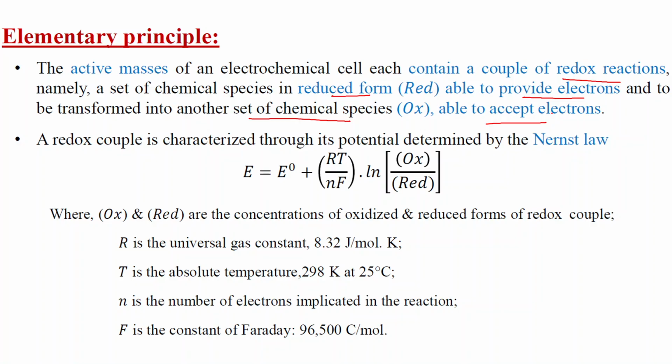And then the ions present in the electrolyte will dissociate and move towards the respective electrodes, as the separator does not allow the movement of any electrons. So the electrons move through the external circuit, which is responsible for the flow of current in the external circuit, and this current is used for lighting up a load.